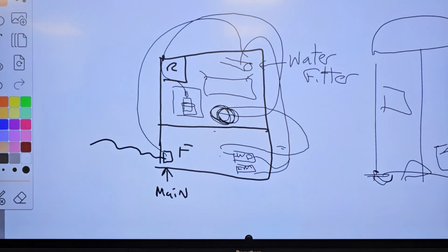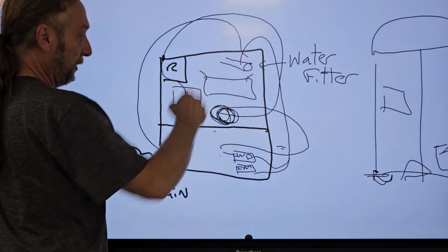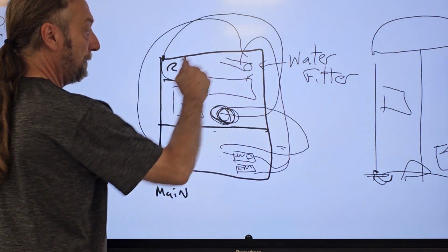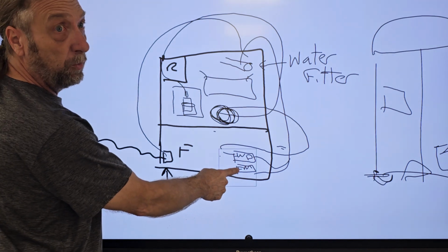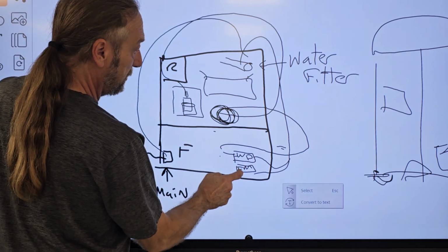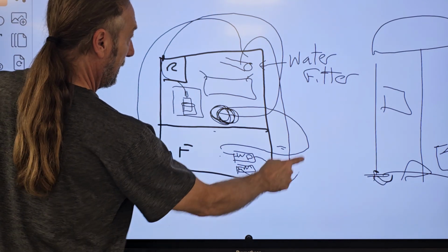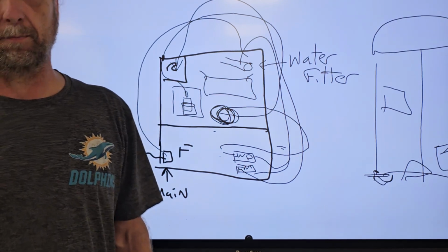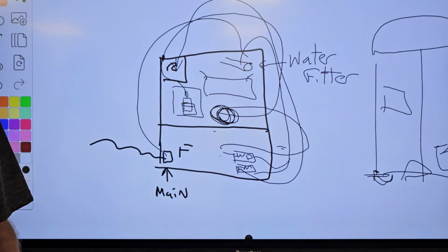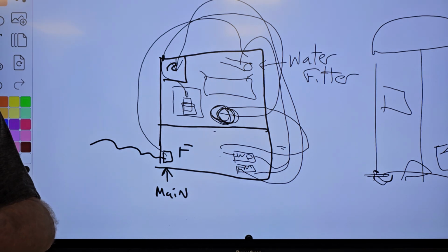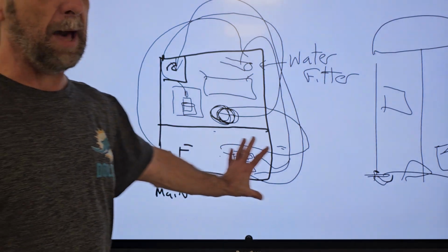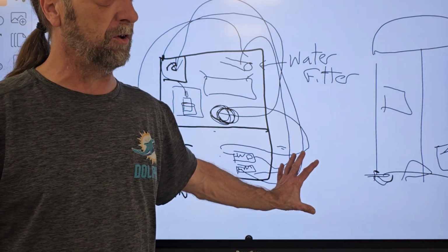Okay? So look at the water flow. Here the water valves, tank, and back. So this ice maker one will go out the refrigerator and run right up to the ice maker up here and come down through the top. Let's go take a look at the routing of the water lines on that unit for a minute, and then I'm going to go back and show you electrically what happens with these valves and something you need to know about, okay?